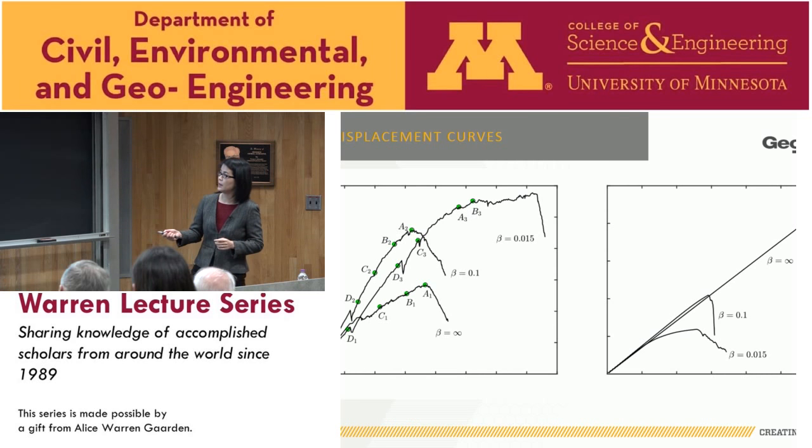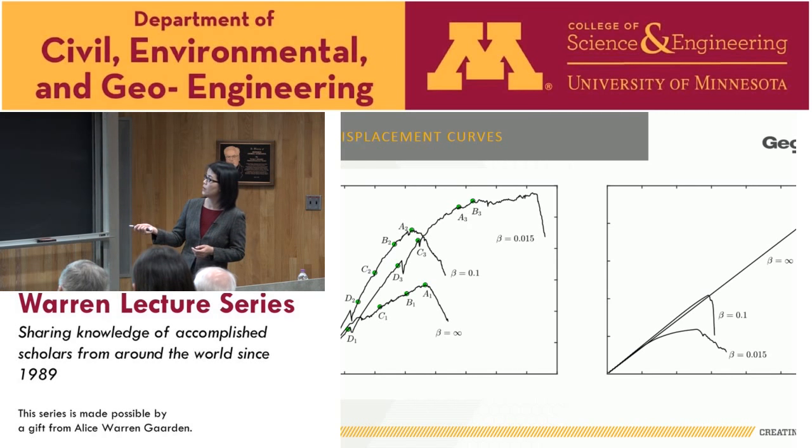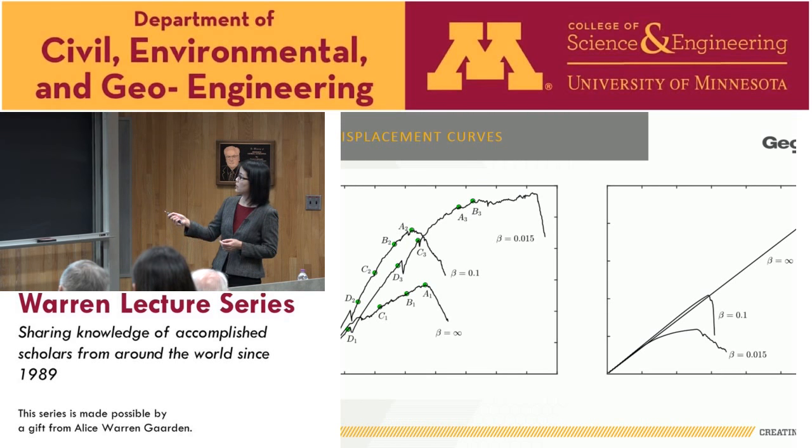So the force displacement, there are fine details about how the failure mechanisms affect the Brazilian tensile strength. One of the things you can notice is that the tensile strength, this should be stress. The tensile stress in the uniaxial tension increases with beta, but the maximum force in the Brazilian test actually decreases with beta.